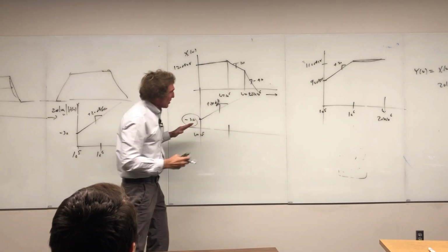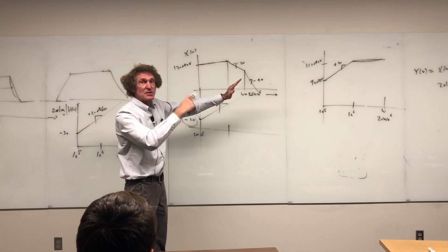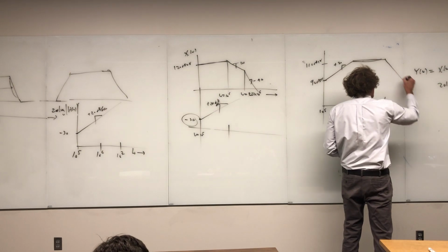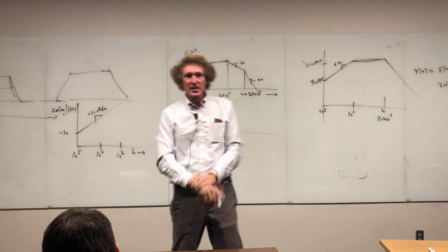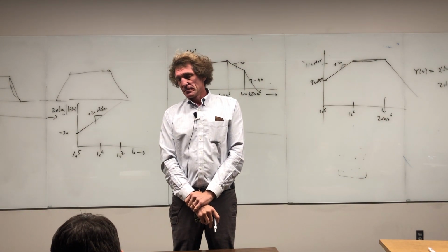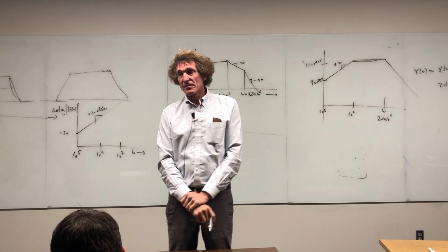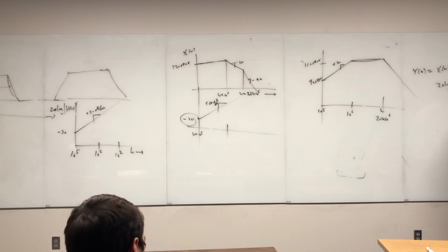Now, this is already going up at 20 dB per decade, but now it's going to go down by 40, for a net minus 20 dB downslope. And this is what the output will look like, regardless of the frequency. Which frequency does he want the thing evaluated at? He wants it at 50 times 10 to the 6th. Now, you're going to have to be attentive to this. People mess this up. They see that drawing, but they don't know how to do this calculation.